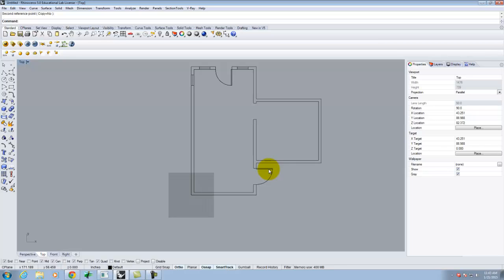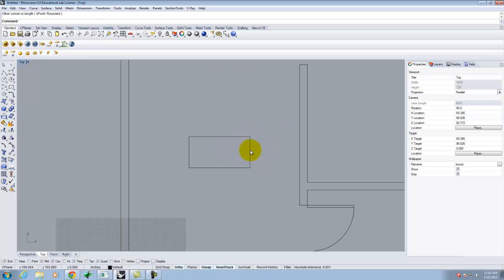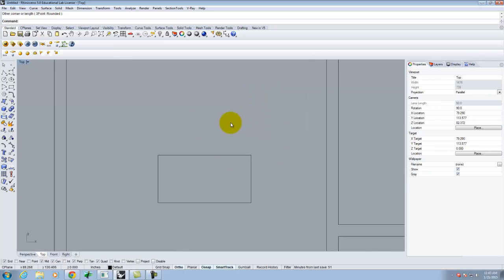Yeah, I'm actually blanking on the term right now, but down below where there's the sink, the little curves to the edges, you do that as a... Yes. Okay. So it's called a fillet. Fillet, thank you. Okay. We have two options. One is a fillet and one is a chamfer. So if, for example, let's say we had a rectangle, and I'm not going to measure it for right now. It has sharp corners on it. If I want the corners to be rounded instead, I can use something called a fillet command,